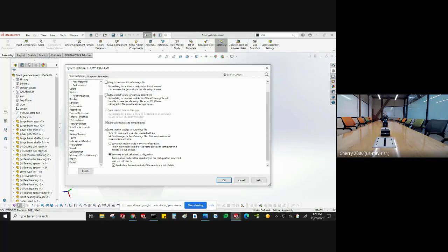The reason that's so easy in an e-drawing is because it's just tessellated data. Tessellation is just triangles. So if you have a cube, that's 12 triangles. If you have a cylinder, it's a bunch of triangles on top and bottom, and then triangles all along the side. And so it starts giving you faceted edges. So it's not a true cylinder when you're doing STLs, but it is what people use for their 3D prints. If you have your STL set fine enough, you can mitigate those facets, but they're always going to be there at some level. The other type of model that people like to have is a STEP file, which has true spheres, true cylinders. There's no triangles involved.